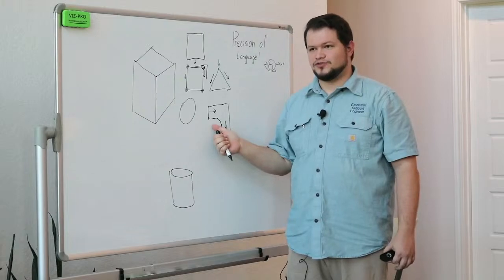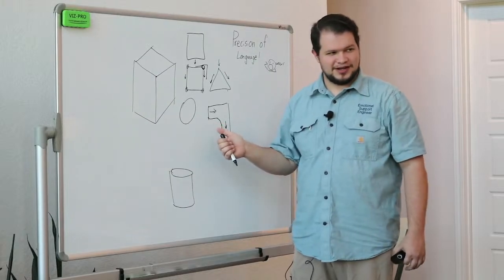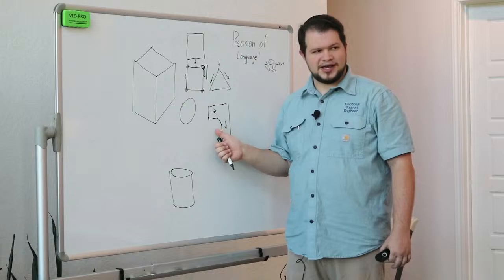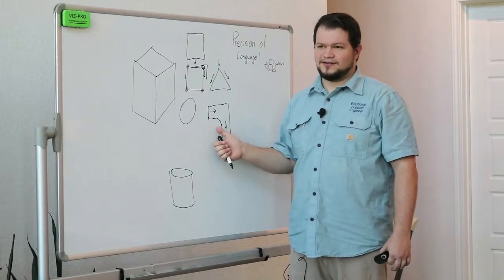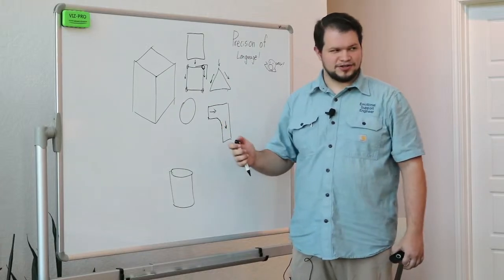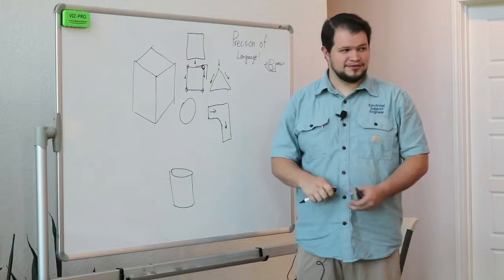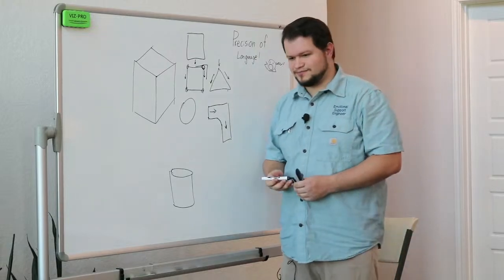This is especially true for 3D prints. So any of your 3D prints that you have straight edges on, you should try and fillet them, but you also have to consider, as we'll get into, how you're going to print it. So you don't want to necessarily fillet everything.